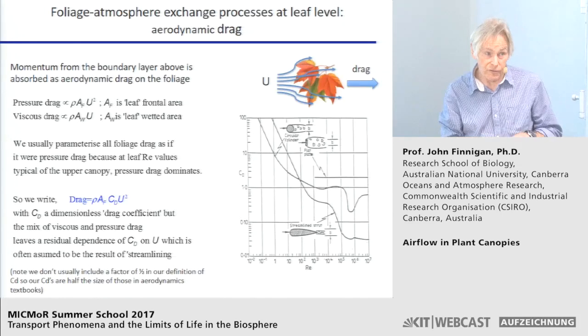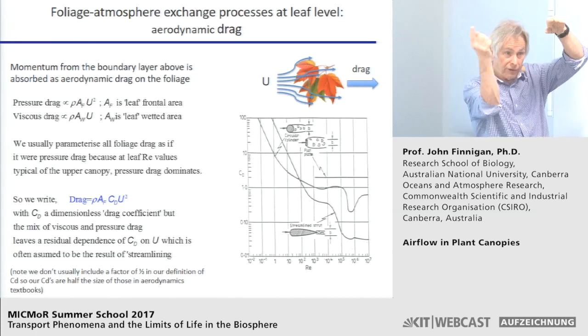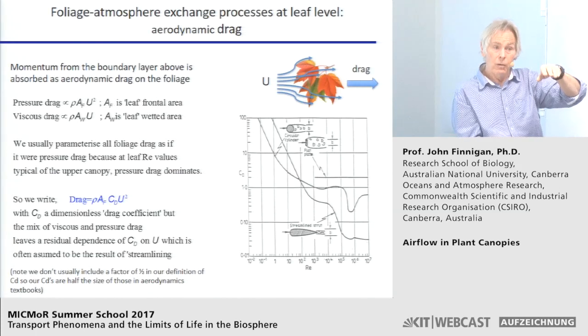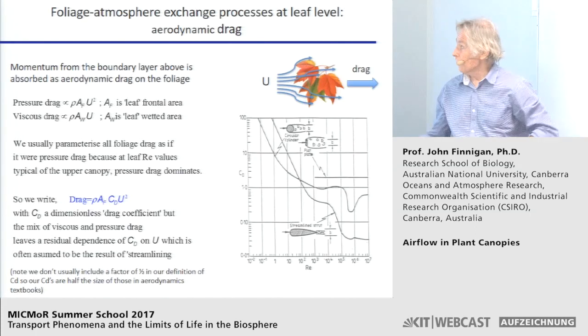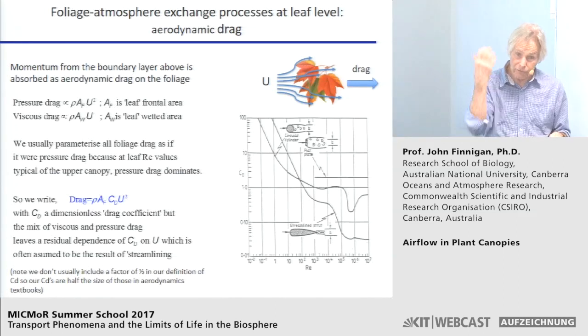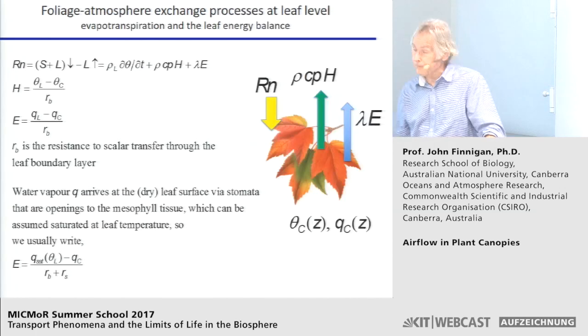What does happen is, as the wind speed decreases, then because of the exponential profile, more of the canopy has leaves in the region where they've got more viscous drag than they would otherwise have, and so the drag coefficient appears to rise. It's not as much drag, but the coefficient appears to rise. So you can be very confused about that.